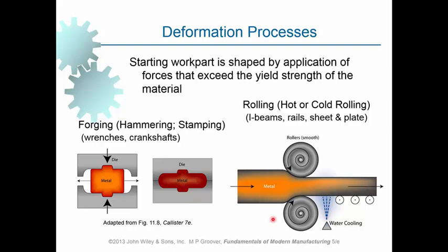And in this process here, we've got a sheet metal which is rolled between two opposing rolls, and what happens is that the thickness of the sheet metal will be reduced to the distance between the two rolls, and also it may have a different shape. If you take a look at the profile of the shape, sometimes it is flat, sometimes it will have a non-flat shape. We can change the shape and also size of the rolled steel or any metallic material to the desired shape and geometry. We will discuss both of these methods in one of the lectures in this unit.